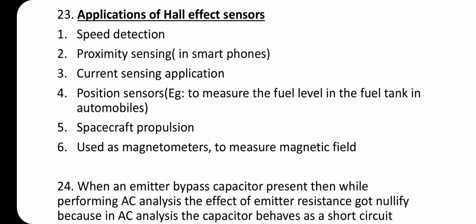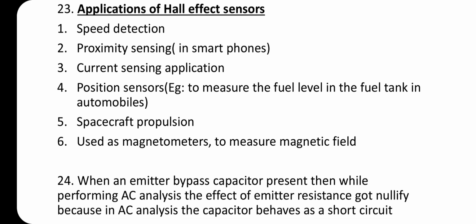23. Applications of Hall effect sensors: speed detection, proximity sensing in smartphones, current sensing application, position sensors, for example to measure the fuel level in the fuel tank in automobiles, spacecraft propulsion, and used as magnetometers to measure magnetic field.